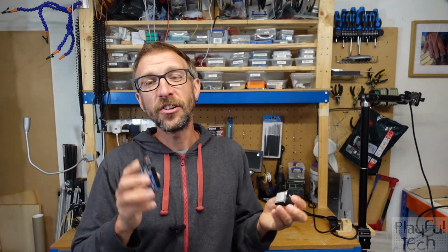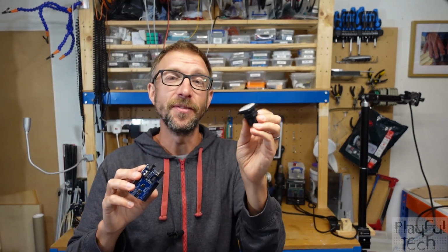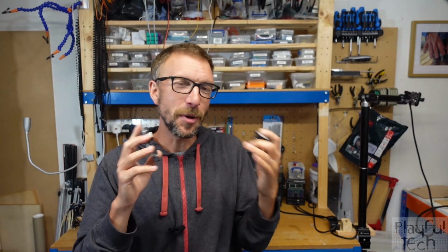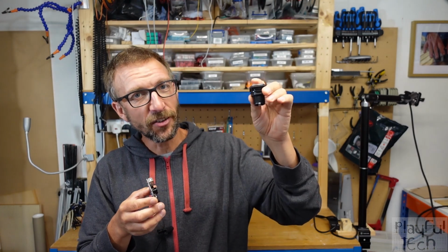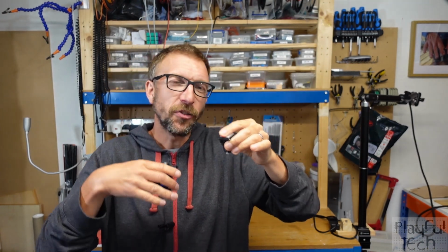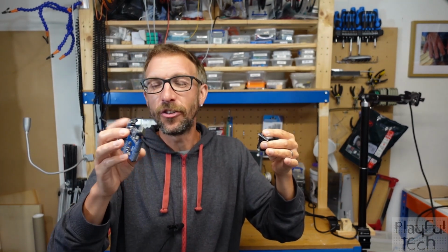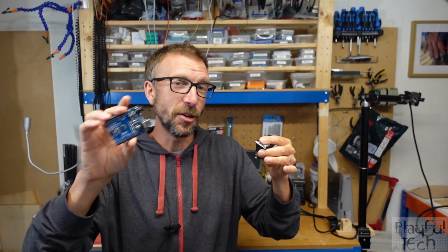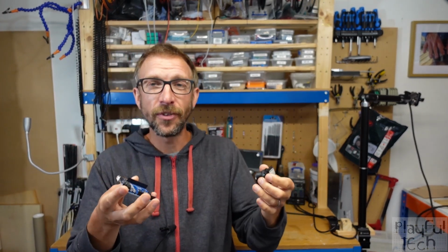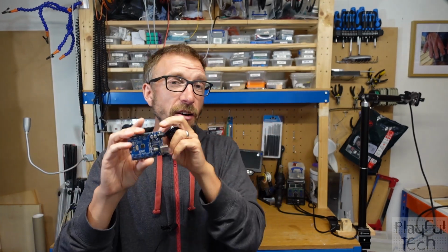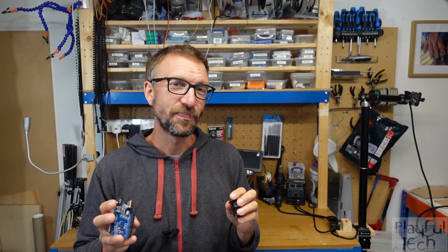Now, one of the first digital inputs you might try to read on a GPIO pin is a button. And one thing that sometimes gets people confused is that in our heads it feels natural to think that when a button is pressed, that correlates with something being on, so you tend to think that that would make a connection to a high signal to be read at a GPIO pin. Then when the button is released, it breaks that connection, turning it off, and we associate off with a low signal instead. But that's not the case.